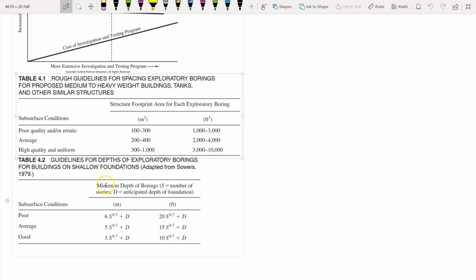So if the budget allows, good practice now may be to have every 2 or 3 CPT done, and in some very important locations, for example a high-rise building, right at the center of the building, you may want to have both SPT and CPT if the budget allows. Or if you cannot, at least have the SPT so that you can collect soil samples for that particular location, and at the surrounding or next locations, you may want to have a CPT. So SPT and CPT information can complement each other.